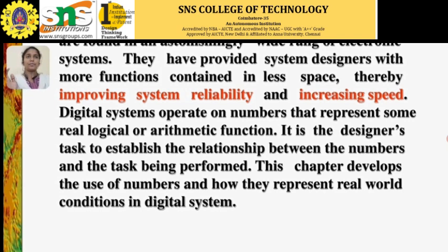Now the overview of how a digital system processes discrete information. A digital system handles data in discrete states, typically binary values, zeros and ones, as opposed to the continuous variations of analog signals. This simplifies data representation and processing. The processing mechanism uses logic gates and sequential elements like flip-flops to perform operations like addition, comparison, and data storage. These operations are executed on binary data, enabling precise control.